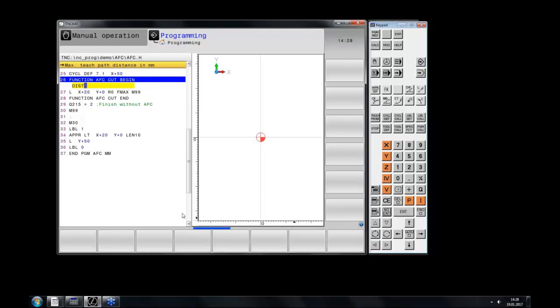For distance, we say 200 millimeters, because we are doing a trochoidal milling. And there you just need to calculate the length of the radius, because we are always doing a circle movement, so that we have enough distance for learning there.